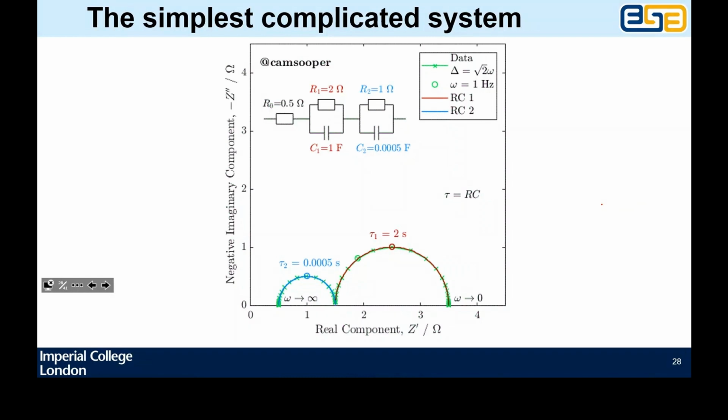Frequency doesn't change anything. But the capacitor, the ease with which you can pass through and back through a capacitor does depend on frequency. Okay, 1 over i omega C. So as the water, or the electrons, is choosing which path to go down, it's going to depend on the frequency, because it's not going down, it's going backwards and forwards. It's going to depend on the frequency at which you're trying to do that thing.